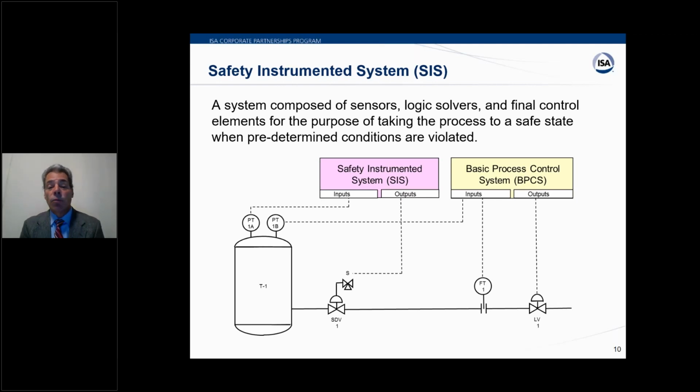So the basic process control system, which could be pneumatics, single loop controllers, PLCs, a DCS, hopefully those acronyms are well known, is what is controlling the process. You have your sensors, your logic, your final elements, and controlling temperature, pressure, level, and flow. So a simple question I like to ask people is, how many of you believe that the control system is perfect and will never fail? And that usually results in grins and giggles, and everyone realizes everything fails. It's just a matter of when.